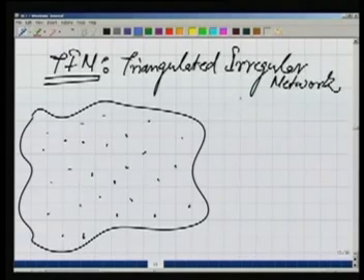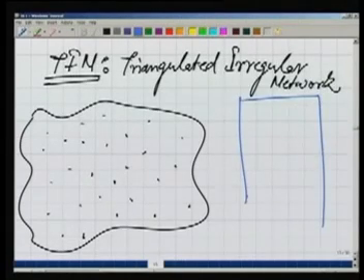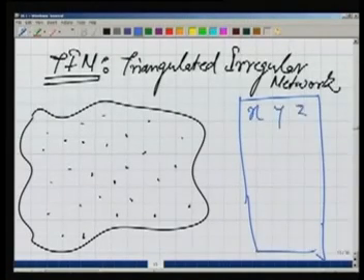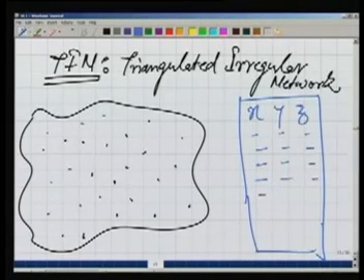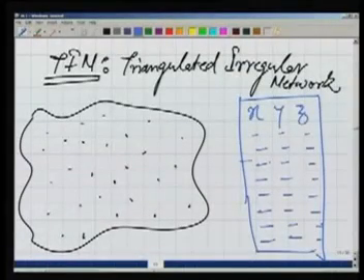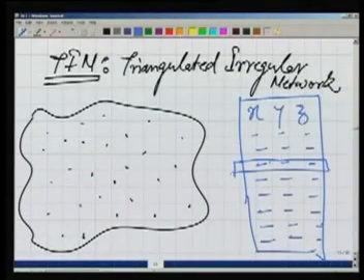Now so far all these points are stored in a file within the computer, and this file is x, y and z, and just the coordinates are stored there. By storing this huge data file in the computer, only a listing of the data is stored. Still it is not a full DEM. It's not a model. Model means we do not know in this data file that for this particular point here, what are its neighbors? Is this point its neighbor? We do not know that.